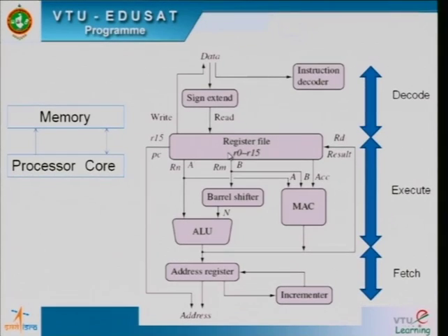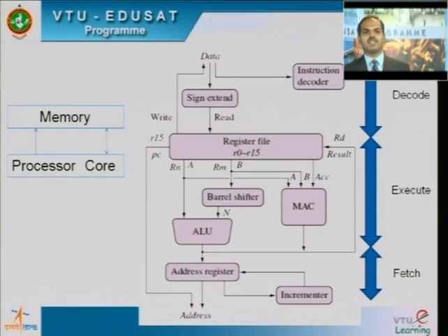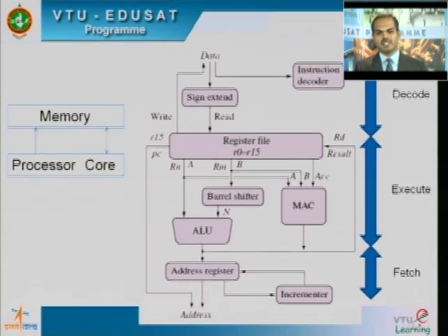This structure is called a load store architecture. If we have to work on two operands, then those operands have to be in the register file, right? This is called a load store architecture. So now whatever data we want to process will come to the register file.